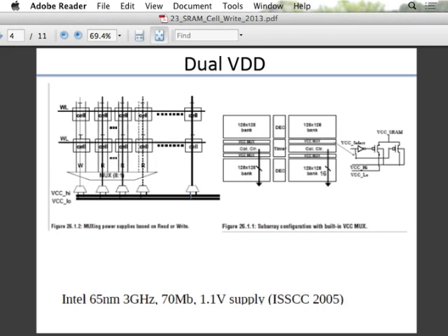So can we use body effect also? We have two different algorithms. Correcting body to zero in a normal NMOS, correcting body to VDD, is the same as VTH, threshold voltage. So when you are passing one through an NMOS, you get VDD minus VTH. If you are changing VTH, then correct. So the question is basically, can we not modulate the threshold voltage? Because if you go back to that equation, it was V cell minus VTH. So why not modulate the threshold voltage of the transistors?